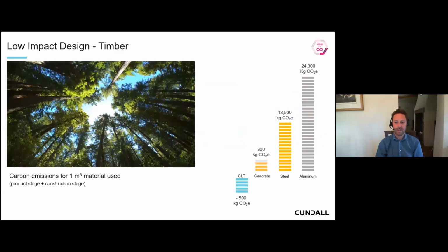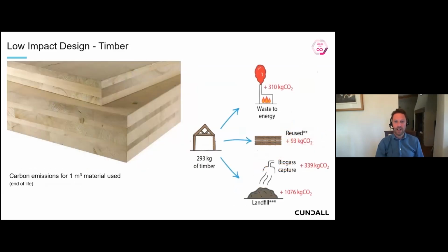And timber, so is timber the holy grail? Well, timber's great because as it goes through the extraction stage or the growth stage, it's capturing, sequestering carbon into it. So actually it comes out at the cradle to gate stage with a negative carbon impact. So it's stored lots of carbon in there, and that's great. But what you have to remember is what you do with that timber at the end of life. So that's why I'm saying it's important to consider the whole stage.